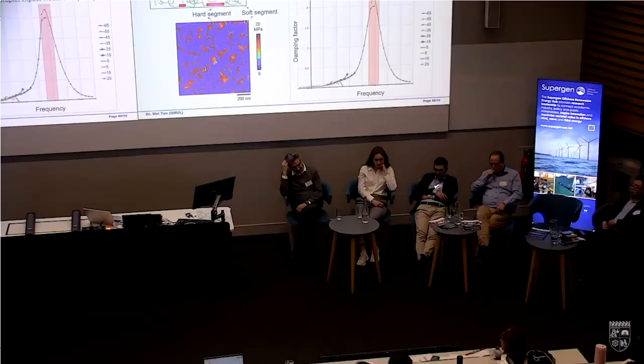So the idea here, or the real novelty here, is that we know the stress wave traveling in the solid depends on how quick the liquid droplet is, 100 meters per second. It has a frequency around 1 megahertz. So our idea is to tune the material such that the peak matches that operational frequency. Therefore, you have the highest damping effect. So that's how we tune our material and optimize the material design.